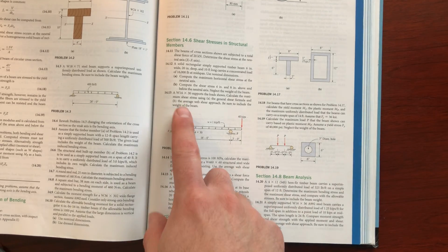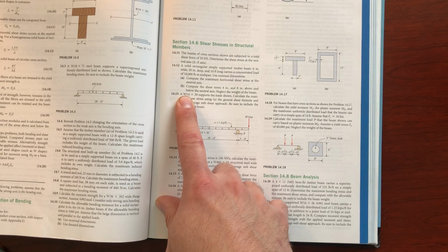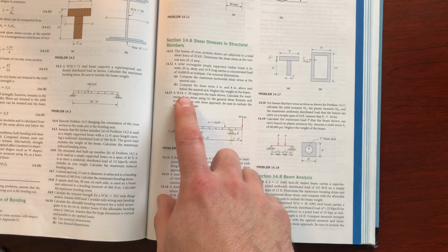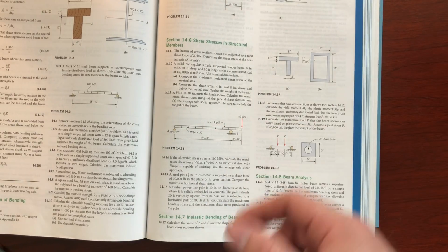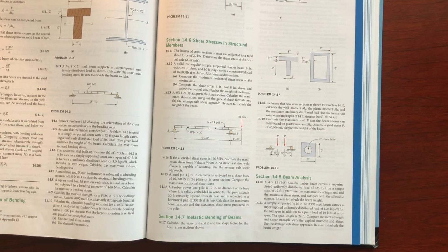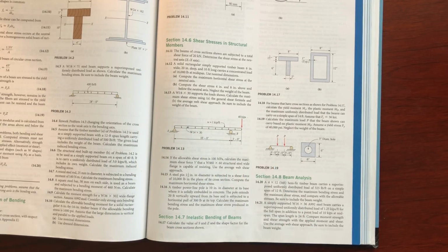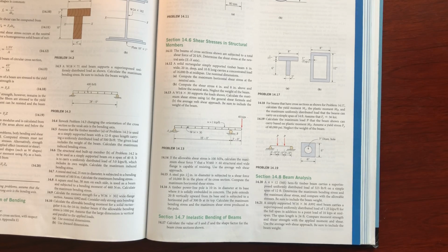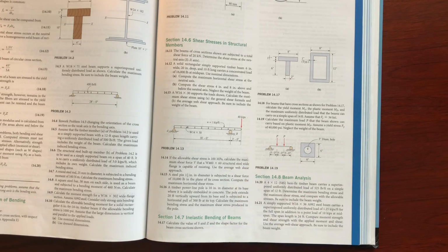So basically, if you recall, the 14 by 30 specifically says that the beam weighs 30 pounds per foot. So we're going to add that 30 pounds per foot to the UDL, that's 1,000 pounds per foot, and we'll up that to 1,030 pounds per foot. And that's going to span 19 feet. That 19 feet times 1,030 is 19,570 pounds, acting as a concentrated load right in the middle. And we need that solely to solve for the reactions of the beam.